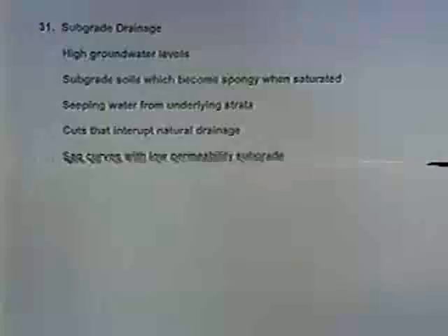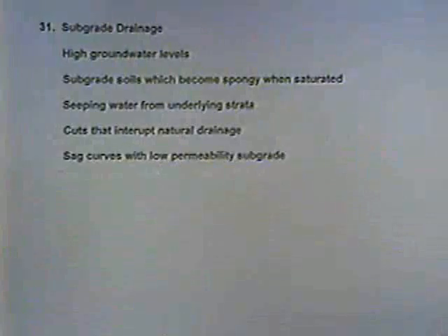There's a section on subgrade drainage and things that you need to look out for. They're listed on this particular slide: you need to pay particular attention to drainage where you have high groundwater levels, subgrade soils that become spongy when saturated, seeping water from the underlying terrain, cuts that interrupt natural drainage, or sag curves with a low permeability subgrade. These are just things you need to look out for.